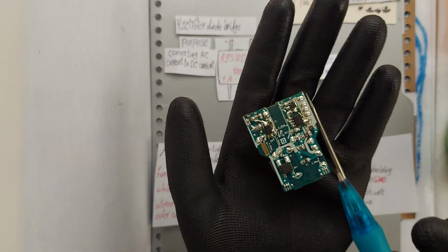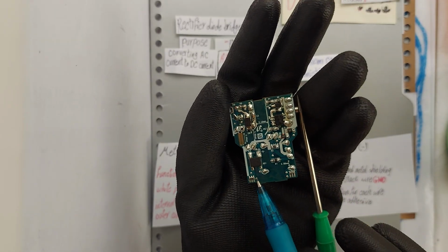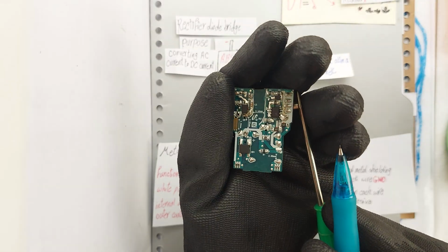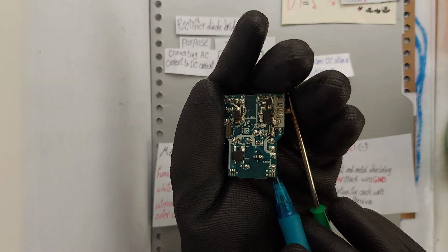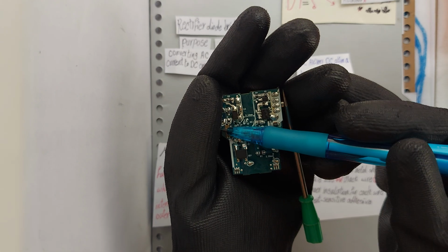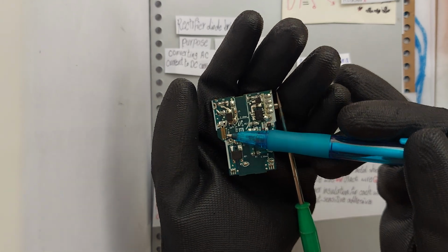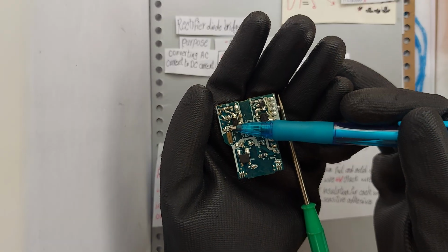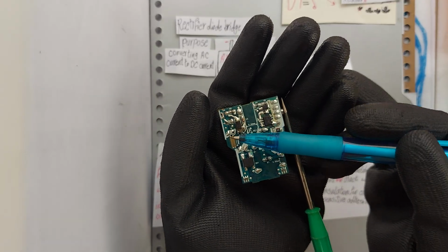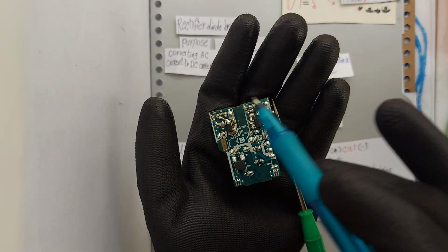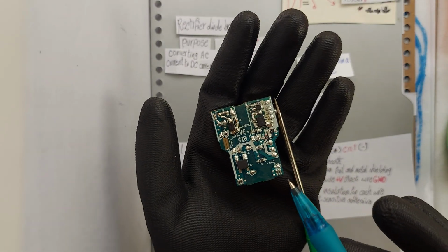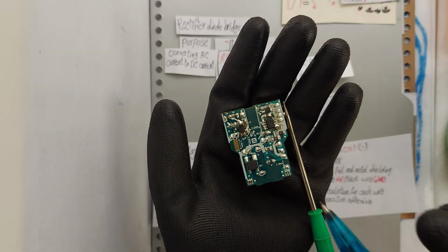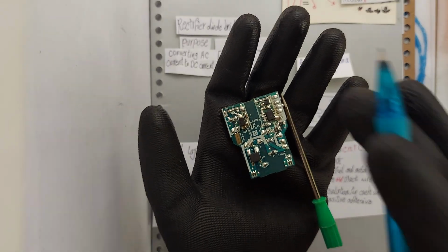On the back of the board, the two square areas, as you can see, at the bottom of the board are where metal pads are soldered, transferring current to the device. We have golden slots. These slots are used to align pin spacing during automated assembly, helping the manufacturer place components precisely. And solder joints, as you can see. These silver points securely connect components to the board. If done well, the charger will work for years.